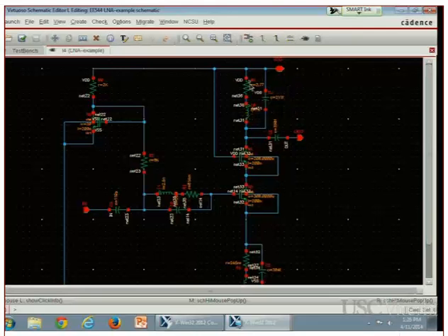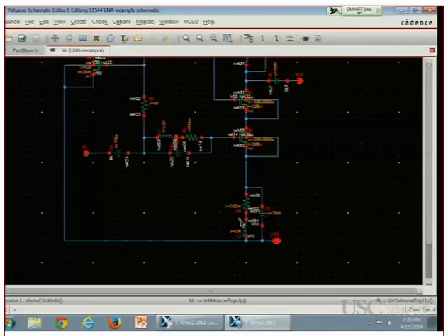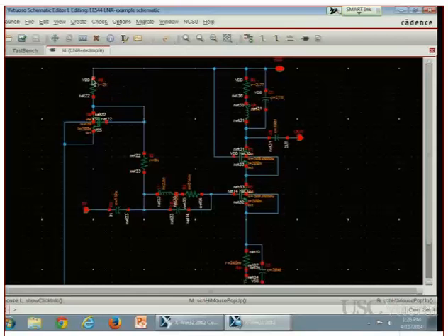Value that you want. So this is a little tank circuit, and then he's got a cascode of transistors, and then he's got some source degeneration down here, and again, the imperfect inductor, same thing right here. This right here is a biasing network, and then on the input here and the output here, he's got these capacitors, and these are DC blocking capacitors.